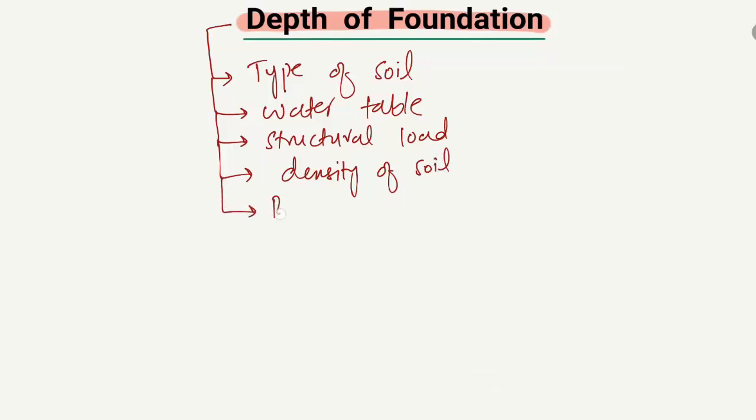The last one is the bearing capacity of soil. This is one of the important factors for determining the depth of foundation. If you are using soil of higher bearing capacity, then you provide a lower depth of foundation. If the soil has lower bearing capacity, then you have to increase the depth of foundation.